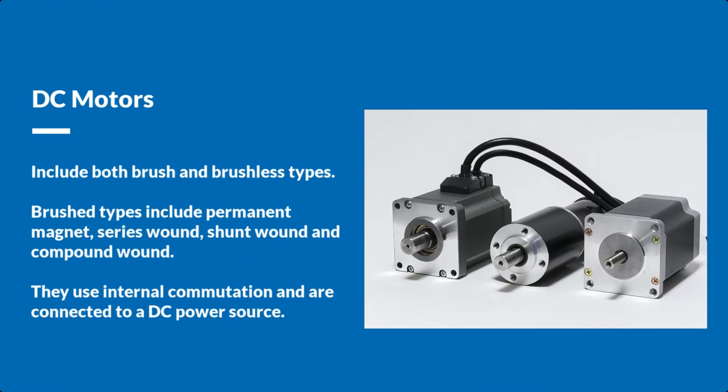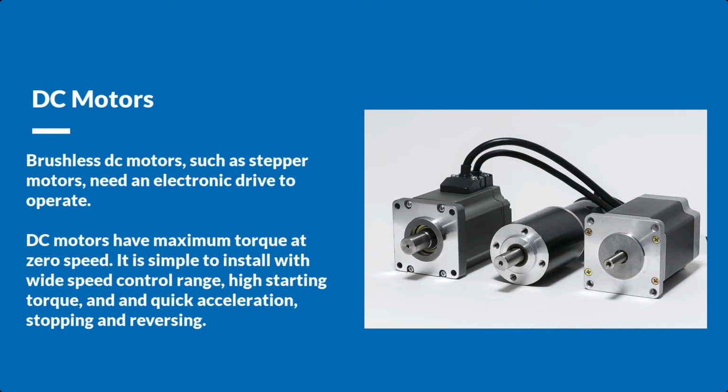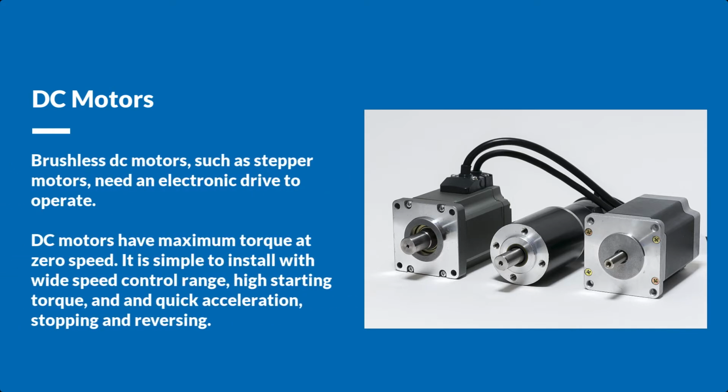DC motors include both brush and brushless types. The brush type, such as permanent magnet, series wound, shunt wound, and compound wound, use internal commutation and are connected directly to a DC power source in order to operate. Brushless DC motors, such as stepper motors, need an electronic drive to operate.